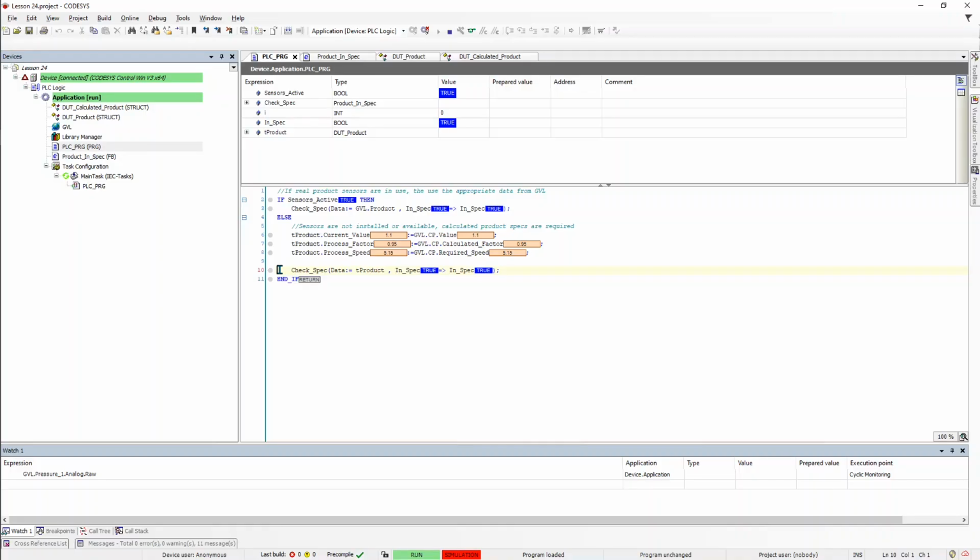While the totalizer function block already does that for a flow meter because it looks at the flow meter data type, we could pack information into a temporary flow meter data type to make use of that block without having to redesign a whole new function block just because we're not using a flow meter. And this is a much simpler version of that.